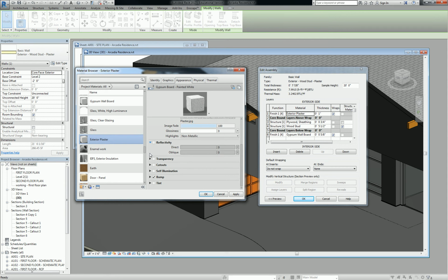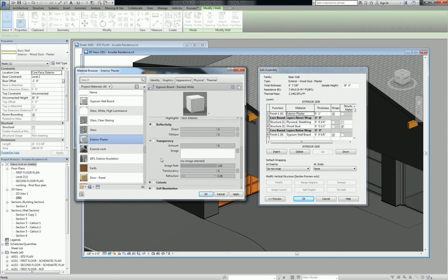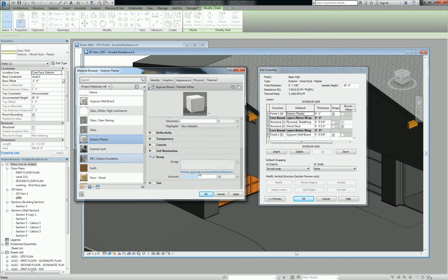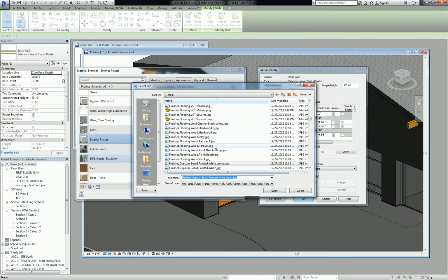You can do all of the same stuff that you do on other rendering engines, where you can bump up reflectivity, transparency, stuff like that for glass or for chromatic materials, metals. If you want to give it some self-illumination, you can actually make the thing shine. But we don't need any of that for ours. Now, bump is interesting. Bump allows you to create and cast extra shadows. What you need to know about bump is that a bump map is not just a material map.